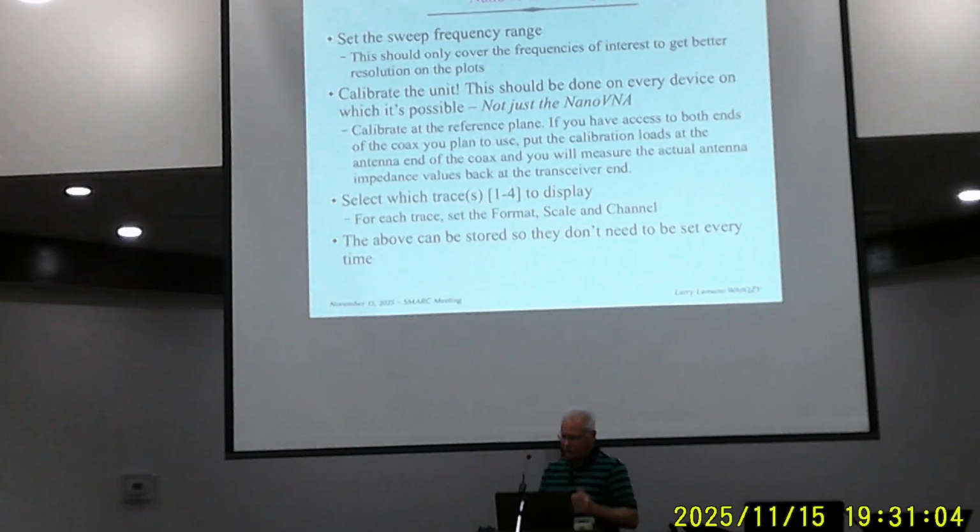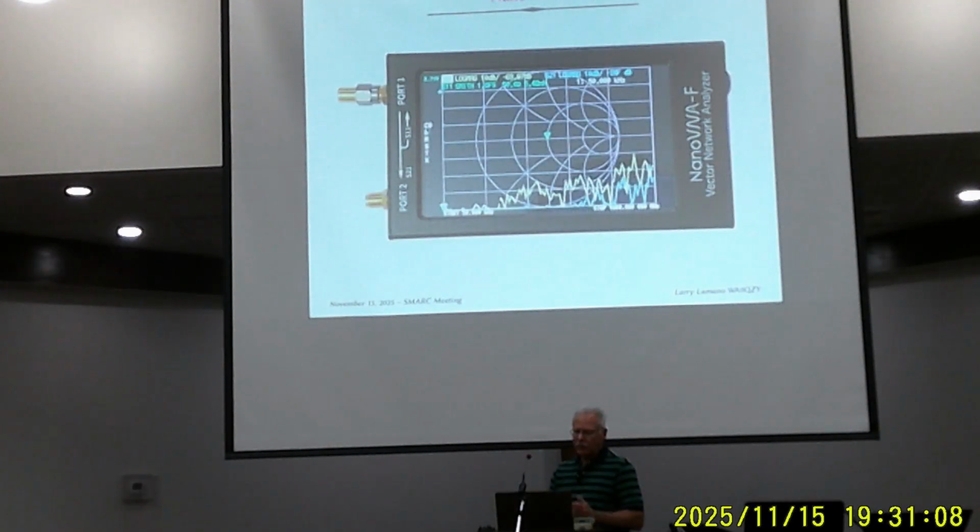Okay, all that looks kind of complicated, but it takes probably 3 or 4 minutes. So all I'm going to say about this is the NanoVNA. I bought a nice cover for it because I'm a klutz. You can see port 1 there. It shows the arrow coming out. If that goes back into port 1, that's the well-known S11 measurement. That's a 1-port measurement. If it comes out of port 1 and goes through into port 2, that's an S21.